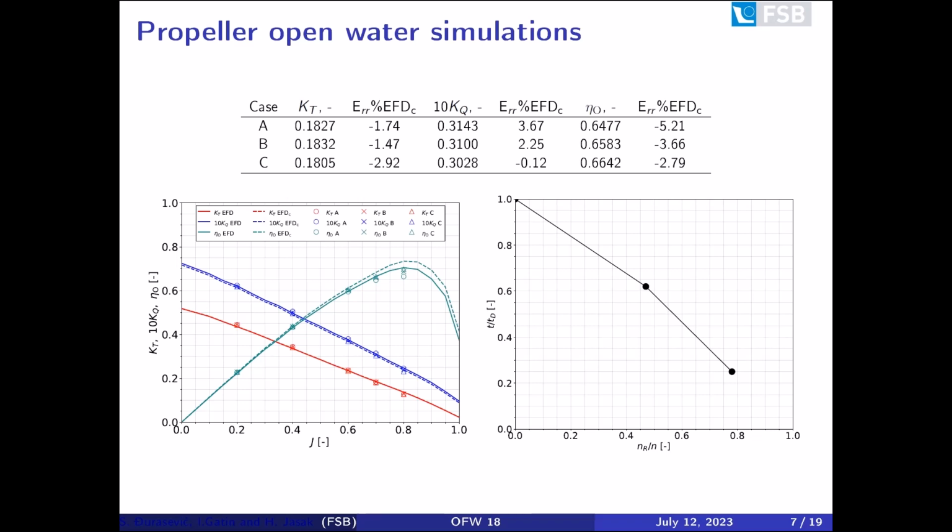By observing the obtained results, a conclusion can be derived that the ratio of contributions from the inertial and non-inertial propeller rotation representations does not affect the integral values of open water characteristics significantly, especially in the case of lower J values, if the figure on the left side is observed, which is actually expected given the uniform inflow conditions. Overall, good agreement between the computational and experimental data is obtained, which shows that the introduced method is capable of predicting accurate integral values.